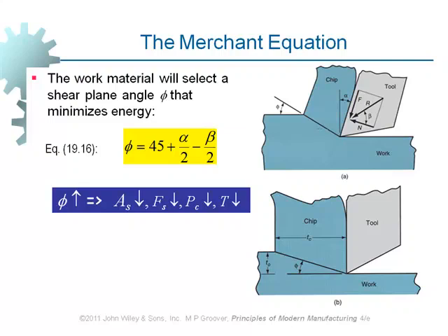It is like designing a cutting tool. When it is sharper, what happens? This is a sharp cutting tool compared to this. Okay? When you are increasing phi, this is what you are doing. You are making it sharper and sharper. When it is sharper, it's easier to take the cut from the material, isn't it? When your cutting tool is sharper, it means that the required power for cutting reduces. Temperature also reduces. And Fs and As are also functions of the sharpness of the cutting tool.